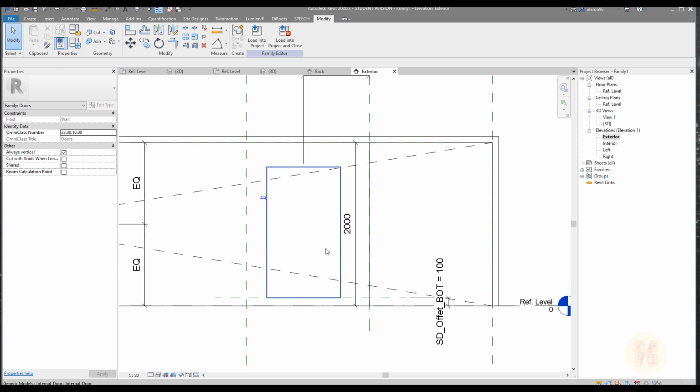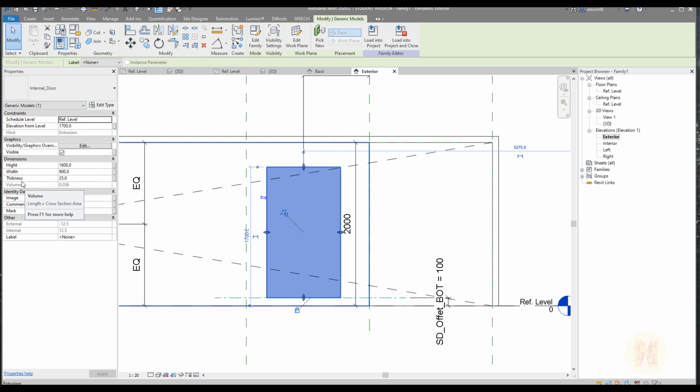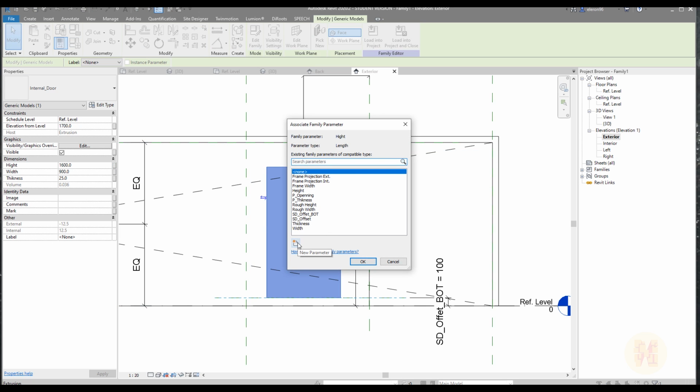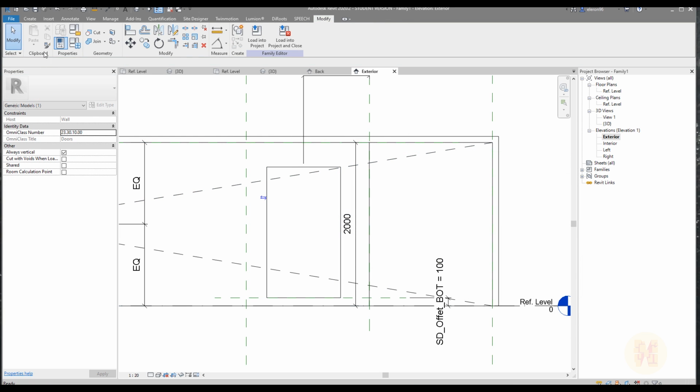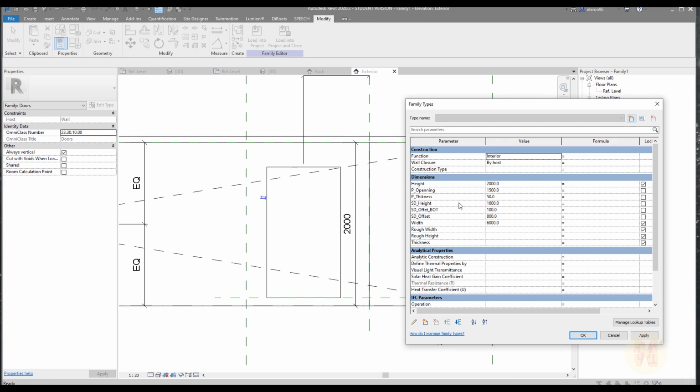Okay, we did it. As you know, the height of my door is now 1600 millimeters. This is not what I want. We should create a new parameter for that one. The new parameter will be secondary door height. And let's make it type 1 2. So now we can make, for example, the secondary door height, let's leave it at 2200 millimeters, and as you can see, it's out of the boundary. Let's make it 1800 millimeters, apply, and as you can see, now everything is correct.